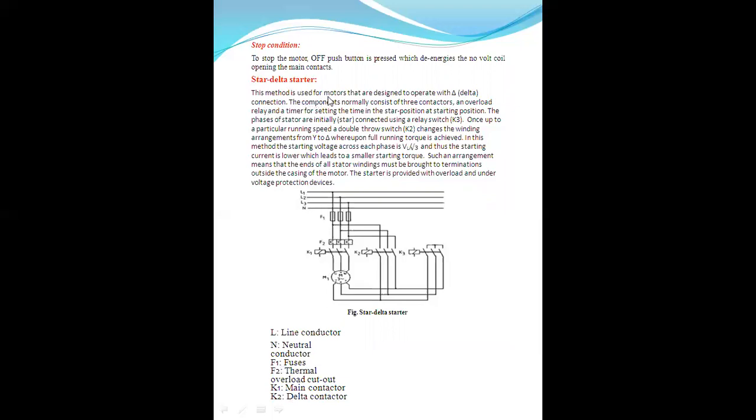This method is used for motors that are designed to operate with delta connection. For that particular motor, this method is generally used. The components normally consist of three contactors, an overload relay, and a timer for setting the time in the start position.